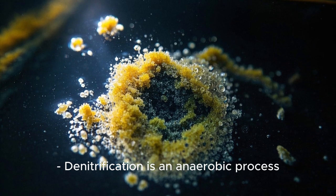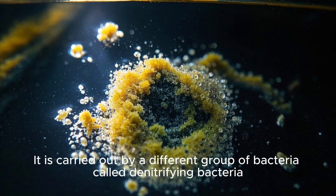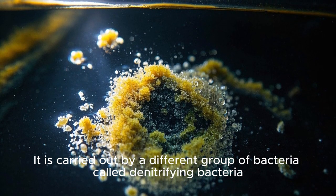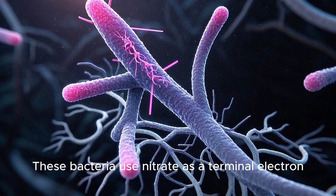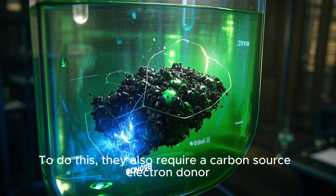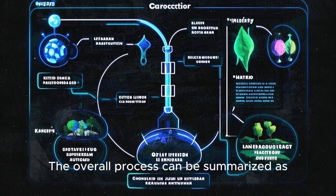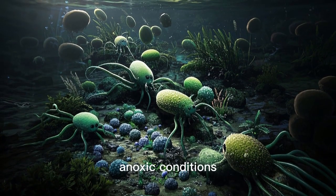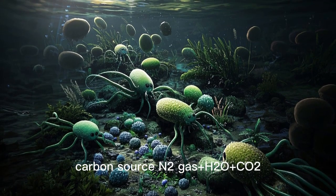Denitrification is an anaerobic process, meaning it occurs in the absence of oxygen. It is carried out by a different group of bacteria called denitrifying bacteria. These bacteria use nitrate as a terminal electron acceptor in their respiration process when oxygen is unavailable. To do this, they also require a carbon source, an electron donor. The overall process can be summarized as: NO3 plus a carbon source, with denitrifying bacteria under anoxic conditions, yields N2 gas plus H2O plus CO2.